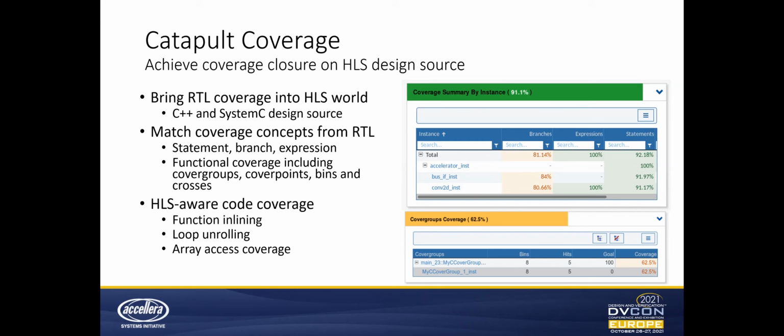And this right here is an example of how Catapult coverage is producing HLS-aware data. The resulting coverage database can treat each iteration of these loops as separate elements, more closely mimicking how the resulting RTL coverage will look. And what this means overall is that you can focus your coverage closure efforts, both code and functional, against the pre-HLS source with the expectation of having very few surprises in the coverage area once you're ready to swap out the design for the RTL when you're doing sign-off.